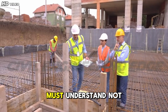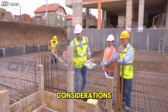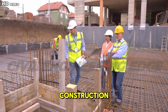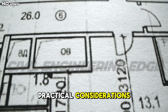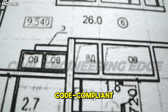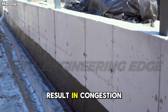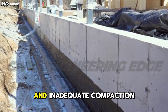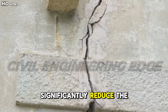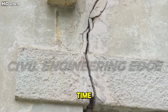Therefore, civil engineers must understand not only theoretical design principles, but also practical considerations and best practices that ensure safe and durable construction. Practical considerations begin at the detailing stage. Reinforcement detailing must be clear, code compliant, and easy to execute on site. Poor detailing can result in congestion, improper bar placement, and inadequate compaction of concrete. These issues can significantly reduce the load-carrying capacity of columns and lead to durability problems over time.